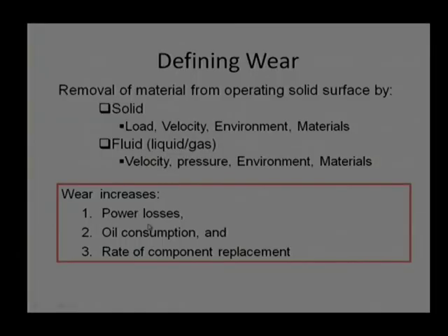If it is happening immediately, then there will be some other cause of failure, it will not be just wear. Or in other words, wear may initiate other causes for spontaneous failure, but wear itself will not cause the immediate failure of the component, but it causes some other problems. So, wear increases the power losses, the friction losses will increase. And here I am talking about measurable wear, not zero wear, or the initial wear, where the asperities are getting damaged or deformed or displaced for the betterment. That kind of wear is good for our machine.